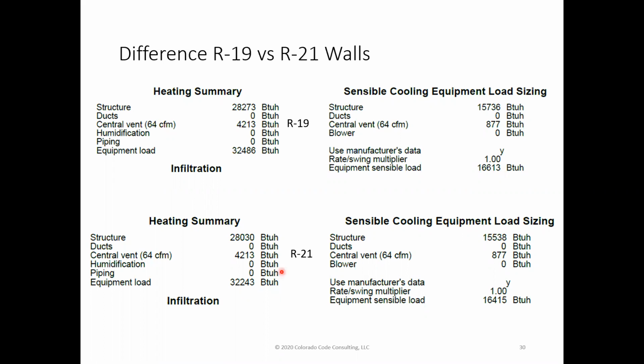If this was the only thing wrong, I might tell them to take it back and say, even if you put the R21 in, it's not going to make much of a difference. It's not going to change your equipment size because you're already putting in the smallest anything anybody's got. It will change your CFM flows to rooms by maybe 1 or 2 CFM, and it may not make a difference at all.